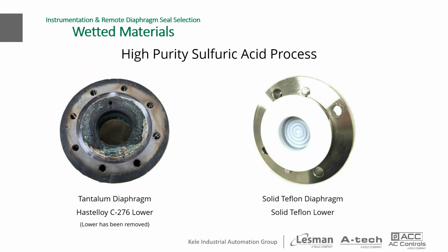I don't want to mislead you. There are challenges when you're working with non-metallic diaphragms. Over time, they can sag or they can cold flow, as they say. Teflon is also just a bit porous, and so process media over time can eventually migrate into the seal cavity. But the result is that they now have assemblies that are lasting up to 4 years. As a matter of fact, we had to make a phone call to see if they were still using seals. They were lasting so long. This is a perfect example of a real solution for a real problem.